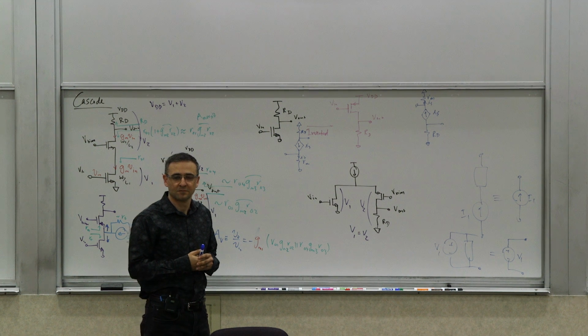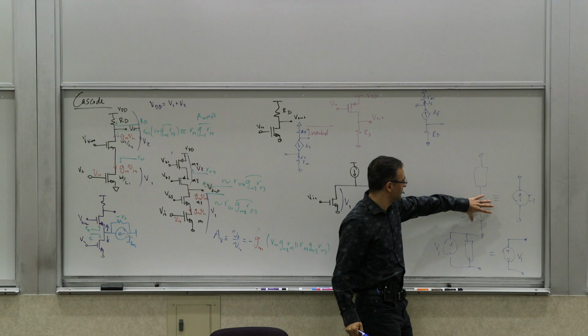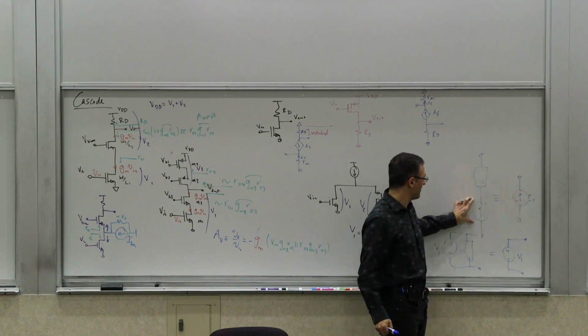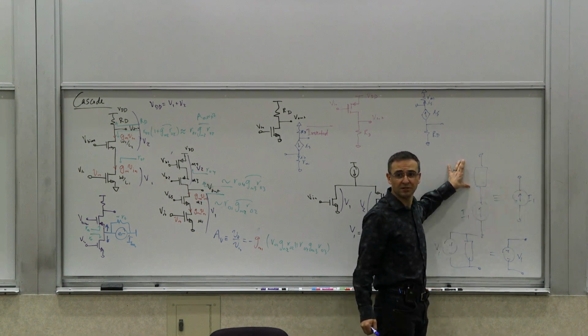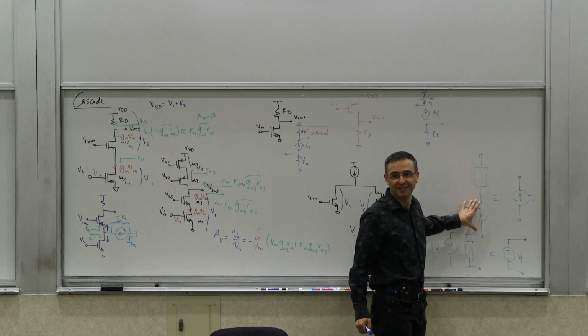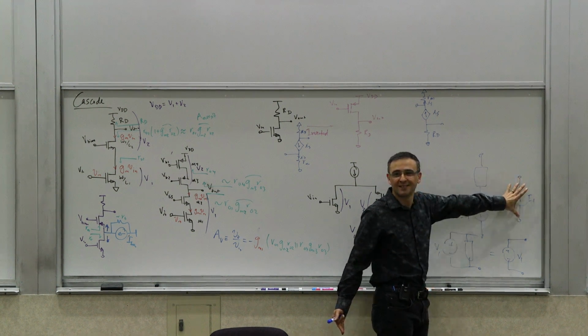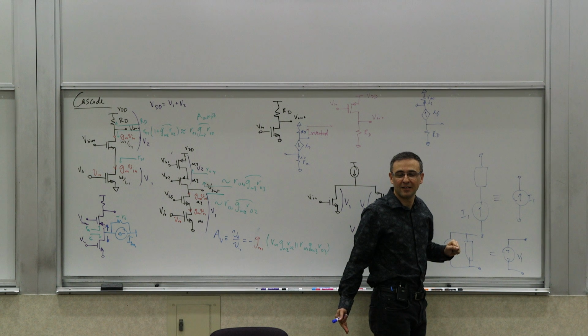Yeah, but when we deal with that in the small signal circuit, this is open. And therefore it's an open circuit in series with some finite impedance. What is the series combination of finite and infinity? What is finite plus infinity? Infinity. So it's an open circuit. So my transistor is open.